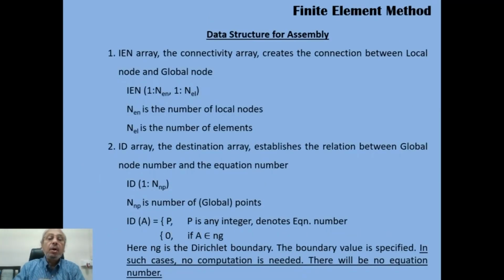So now we have understood the overall formulation strategy of finite element method and how it differs from finite difference and finite volume method. We mentioned finite difference is basically a difference quotient based method, whereas finite volume is basically an integral method, but the weighting function is 1 for each integral.